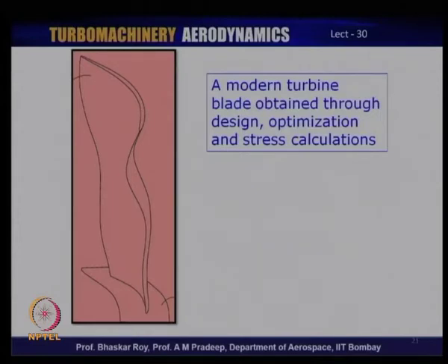It may come out of this kind of shape, typically of LP turbines, where you do not have the cooling technology embedded inside it. So, some of these refinements need to be done through CFD, through optimization between gas dynamics and thermal load and stress calculations. So, you can get final design through very intense analysis process after the first cut design is done through the steps that we have gone through in today's lecture. So, this is how you finally create an axial flow turbine blade.